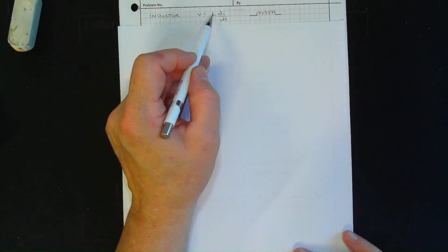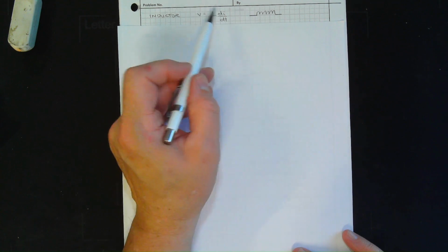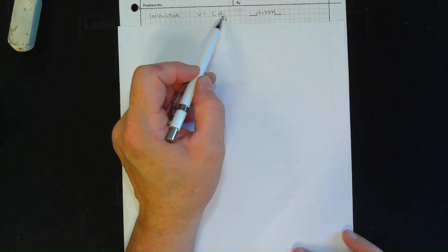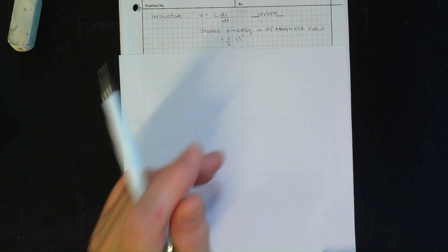All right. And we have one other element we need to add in there. That's the inductor. So here's the familiar symbol. It kind of looks almost a little springy, but the voltage across the inductor is L di/dt. So you only have a voltage across this thing if there are variations in the current. So that's kind of interesting. This stores energy in its magnetic field as opposed to the electrical field, and the energy stored is 1/2 Li squared.